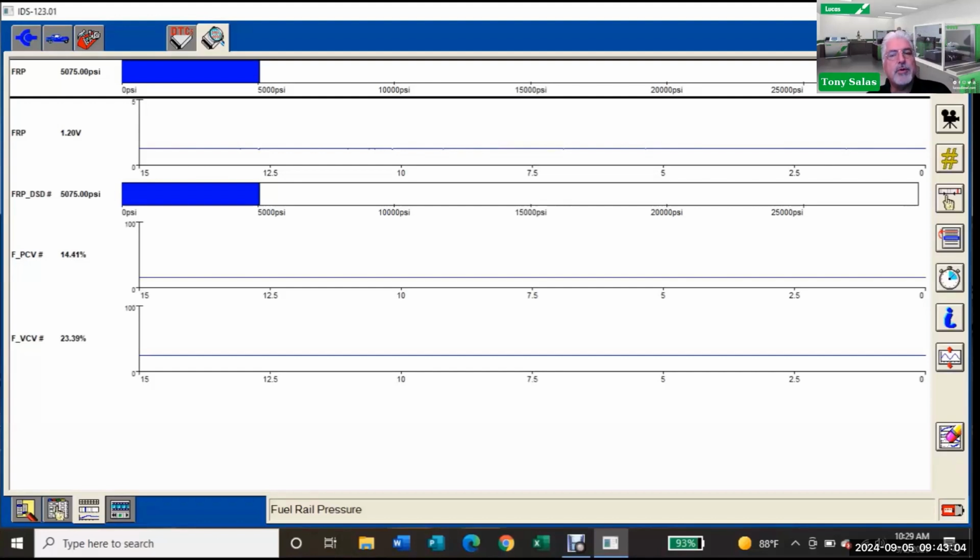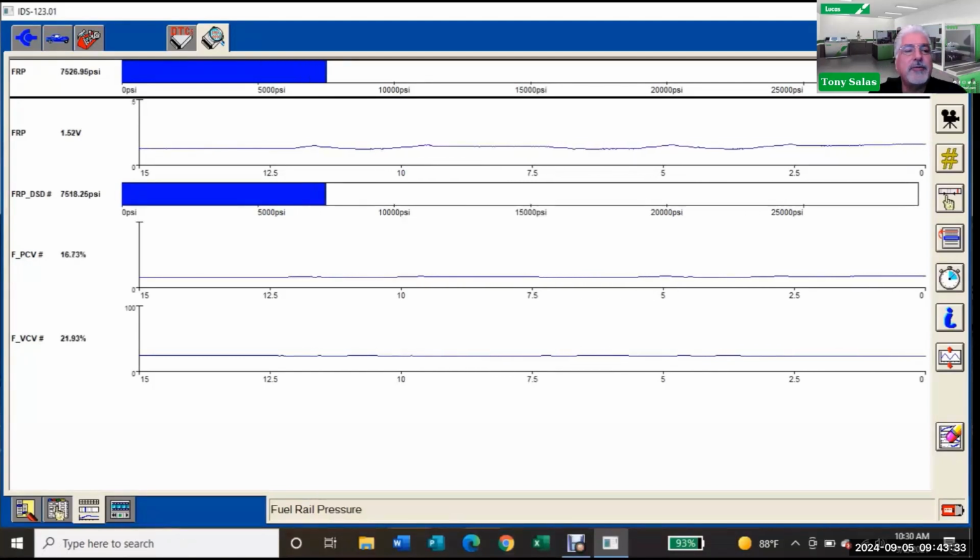because if I'm working by myself, I don't have somebody to look at rail pressure when I'm doing a test drive in case I'm losing rail pressure under load. So therefore I use the bar chart. So as I continue to play this, this reading of these PIDs of the fuel rail pressures, we can see again, and I'm going to give an acceleration here. You can see the desired being followed by the actual. So as I test drive, this helps me say, yeah, I'm not losing rail pressure. The actual is meeting the desired.